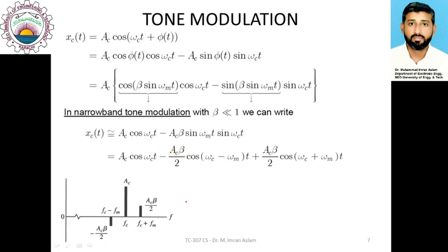The phase angle would be negative here, which is illustrated by this negative curve here, just for simplicity. So this one appears to be negative, whereas in the AM case it has the positive amplitude. So you can see that this narrowband FM case becomes similar to what we have observed previously, that it has one lower sideband and one upper sideband, and the carrier, which is close to the one that we have observed in the case of AM signals.